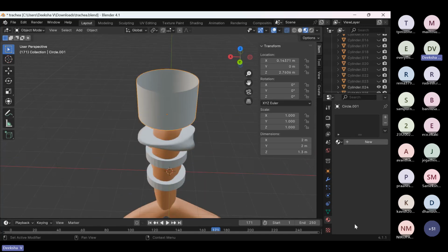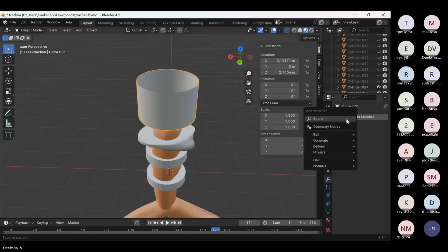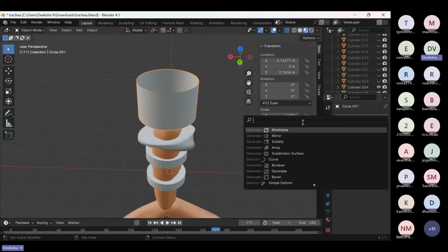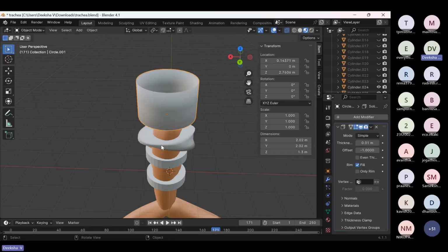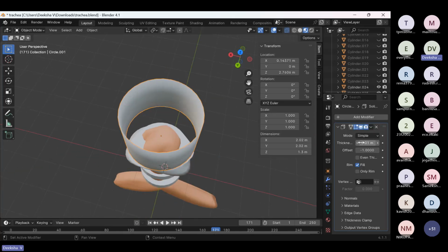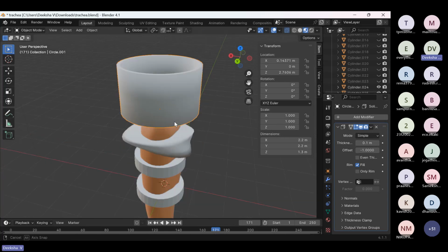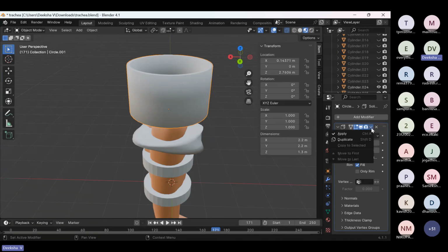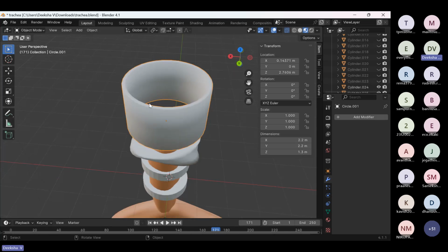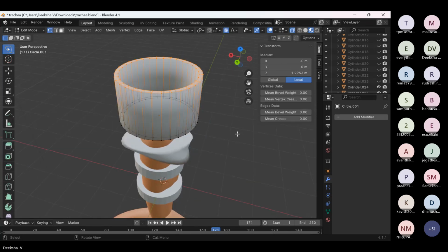since this is only a plain surface and I want a little thickness, I can click on the object. Here you have, again, I showed you materials, right? Same way here, there's a modifiers option. You go there, search for solidify. If you give a solidify modifier, it basically adds a little thickness to your plane. So for now, this is enough. Once you're happy with the thickness, there's an arrow here, just click on that arrow and click apply. So when you go back to your edit mode, this is how it will look.